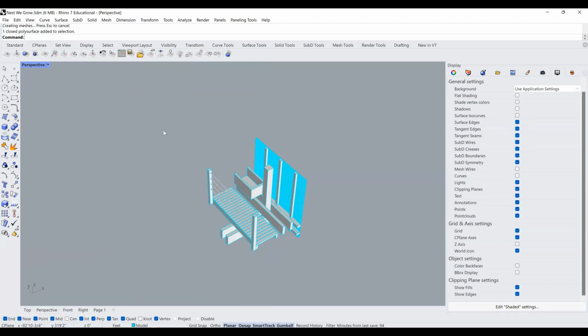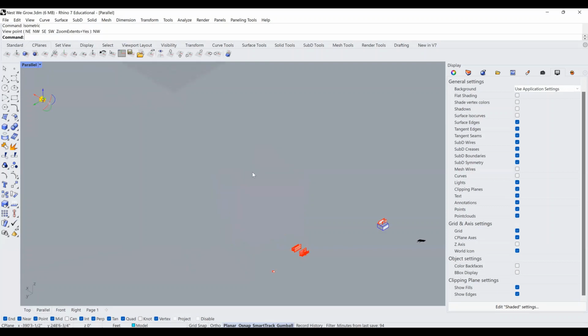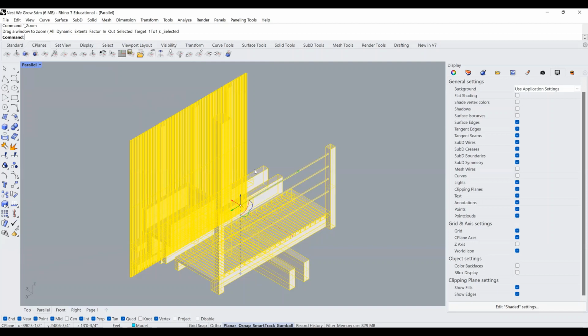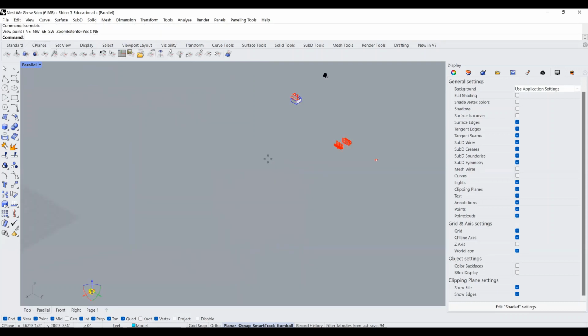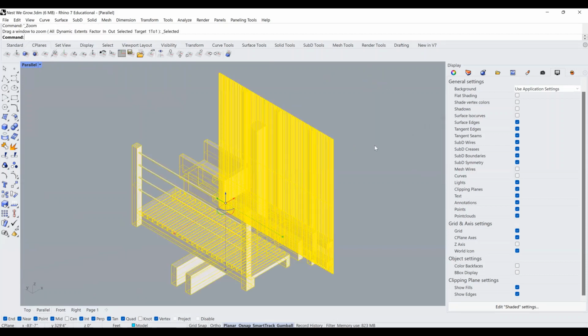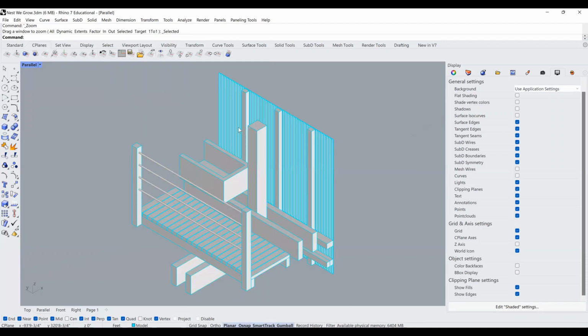So it's going to be this view that I want to capture, and also this view. And the way that I want to look at this is by typing isometric. And let's experiment with which view. So I want to see this view, right? I think the closest view to this is northwest. And ignoring the test runs I have, this is not exactly the view that I want. So I think it's northeast. No, it is southwest, I think. Yeah. So this is the interior view that I'm trying to make the 2D out of, right?